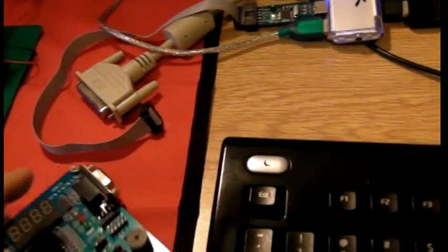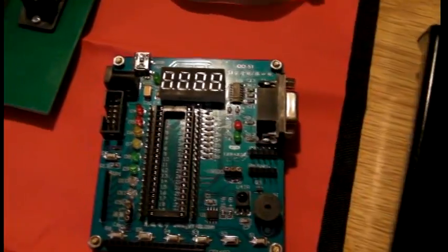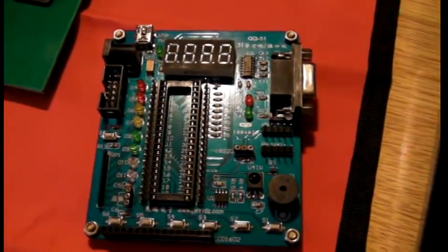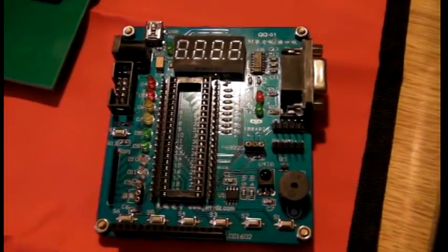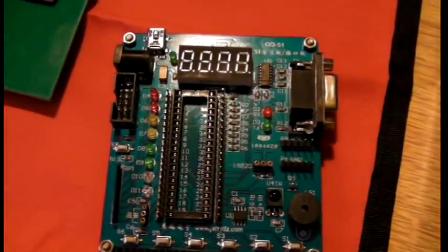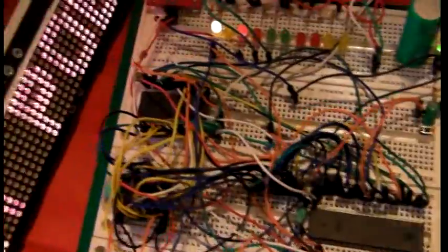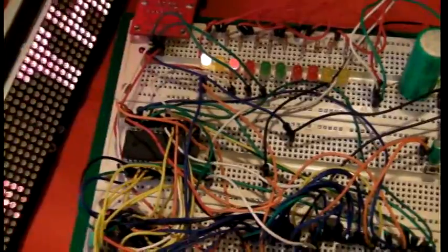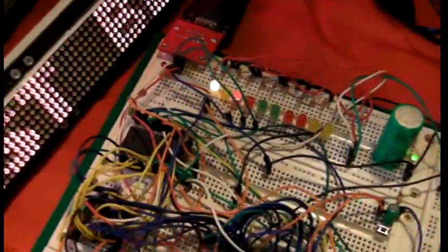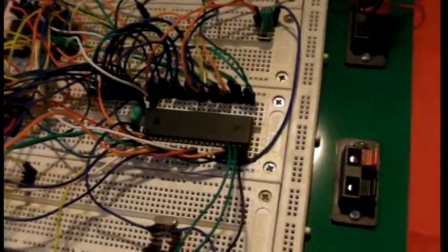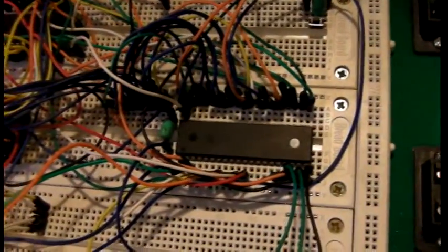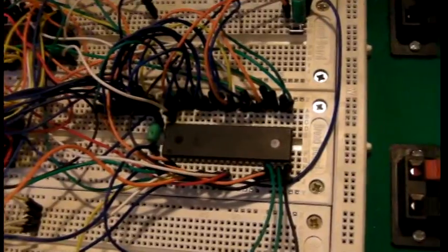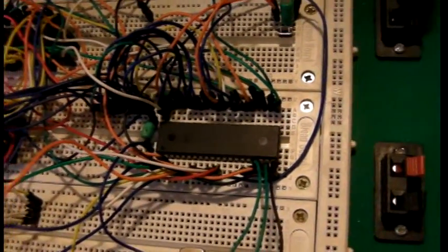This project started on this little development board here that I got on eBay, which I still use as a flash ROM programmer for this microcontroller that I use with this project. However, I had to move the project to the breadboard now because I needed to extend the hardware with external static RAM, 32 kilobytes, because the memory on board of this controller, 256 bytes of RAM, has proven not to be enough to hold all of the text that I need to display.